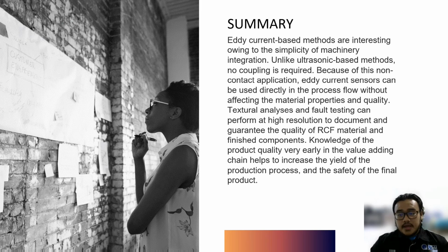For summary, eddy current based methods are interesting owing to the simplicity of machinery integration. Unlike ultrasonic-based methods, no coupling is required. Because of the non-contact application, the eddy current sensor can be used directly in the process flow without affecting the material properties and quality.